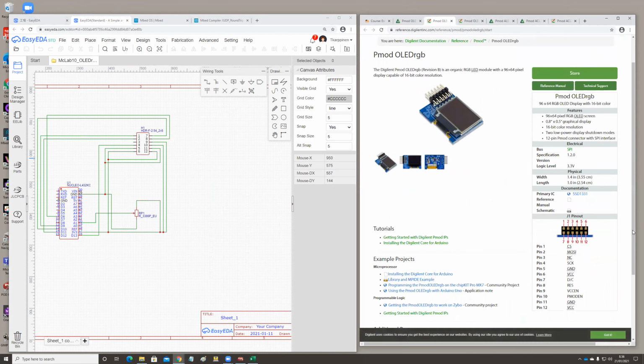We had a look, and it is with the SPI interface, and there are certain pins with the pin names referring to the function of the pin. So chip select, master out, slave in, that's not connected. That's a clock signal, ground, operating voltage, and so on. And then the pin names here. We drew a circuit diagram with the connector for that one.